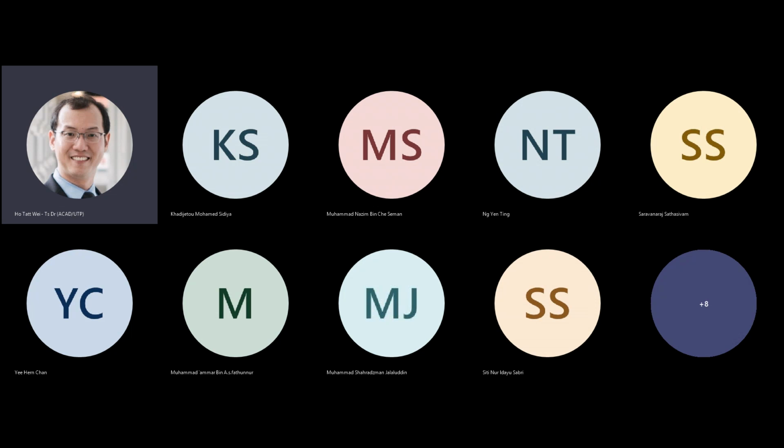How can you do that? Well, you have a relationship between I, which is the current flowing through here, and this is the relationship with VGS, but there's also another relationship, mu C ox over L, I think it's VGS minus VTH, and VDS over 2.